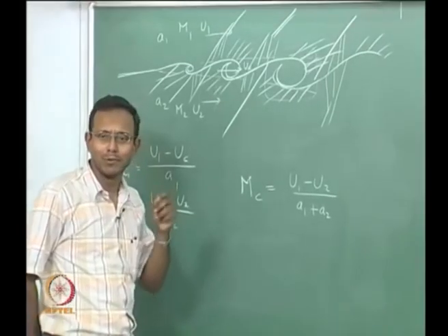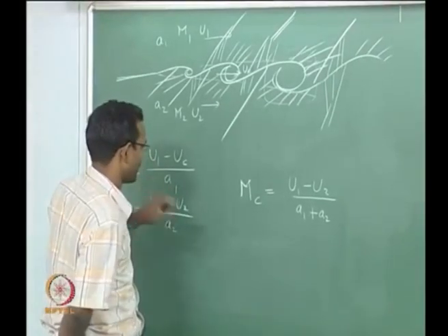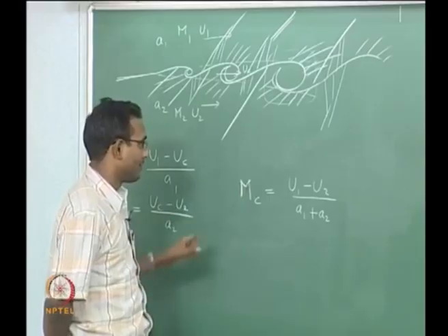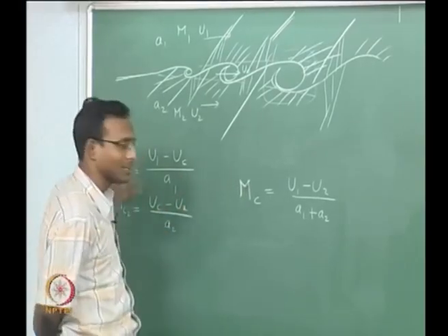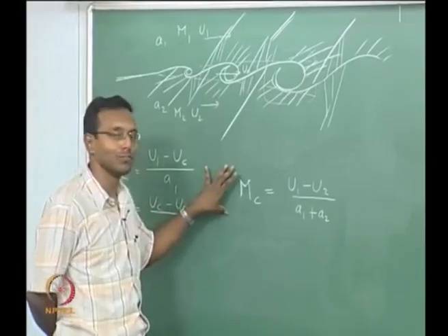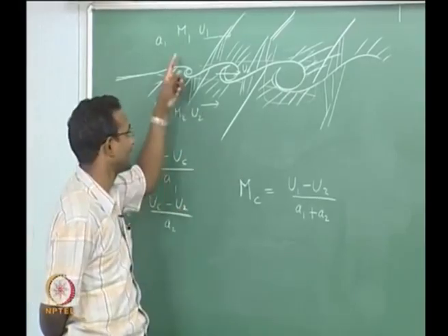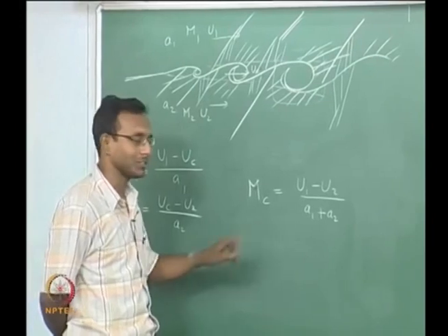There is just a little bit more, so I will go on for 2 minutes and stop after that. So, they found a convective Mach number based on this. Actually, it is based on these two formulae plus the pressure matching condition. I can get to a formula simple enough if my gas is the same top and bottom.